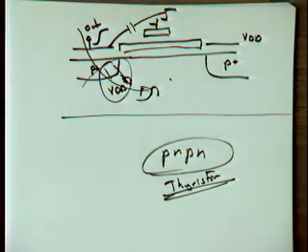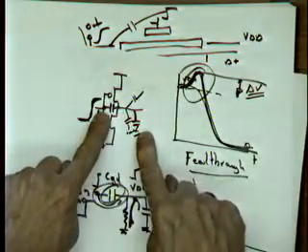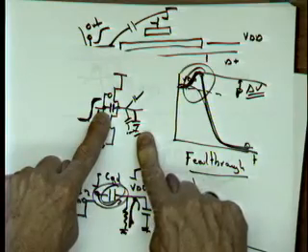Huge amount of current flowing to your substrate. And suddenly you see some smoke kind of whirling up from your chip, and the story is over. You better get a new chip. Okay? So that's why this overshoot is kind of worrisome. If your feed-through capacitor is large compared to your load capacitance, you have to worry.